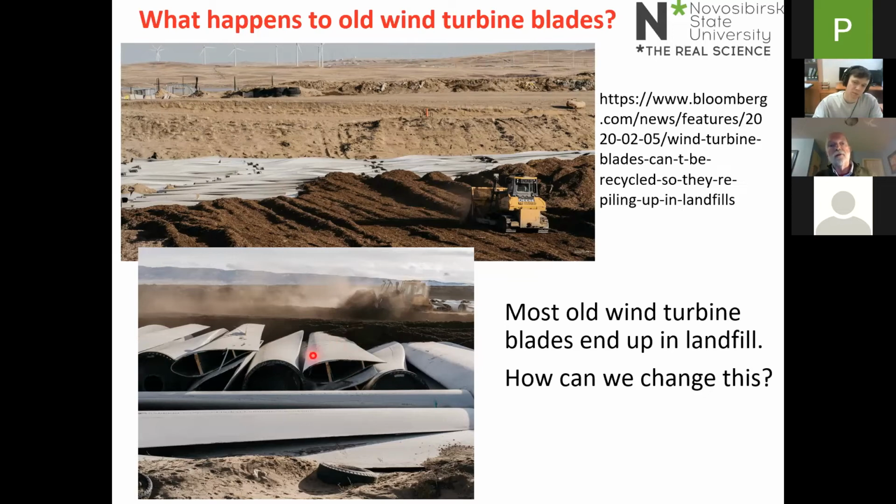There's a big move in the wind industry to make blades from sustainable materials. And those sustainable materials can include things like what are called bioresins, resins that are made from natural materials. Another way of dealing with that problem is to use what's called a thermoplastic resin. And a thermoplastic resin actually melts at a high temperature rather than sets at a high temperature, which is what happens with standard fiberglass. So a thermoplastic resin can be reused. So if you take an old wind turbine blade, in principle, you can melt it and make another blade. So that's one thing that people are looking at.